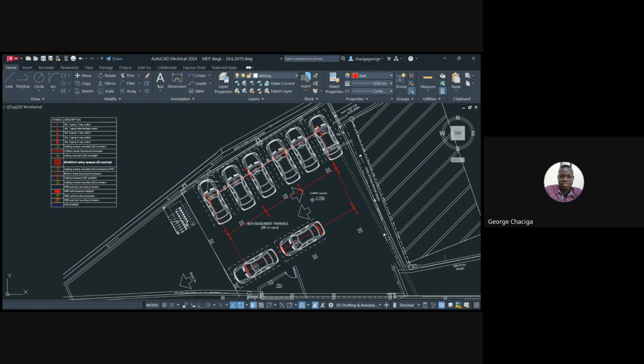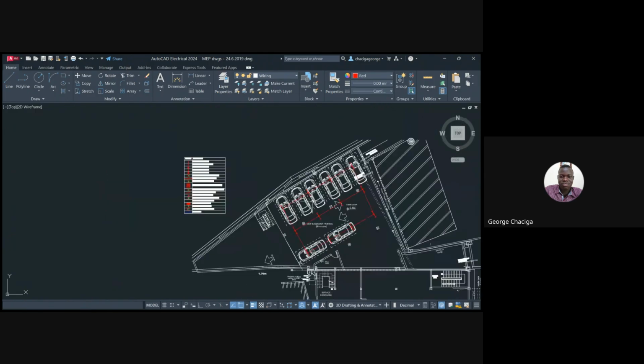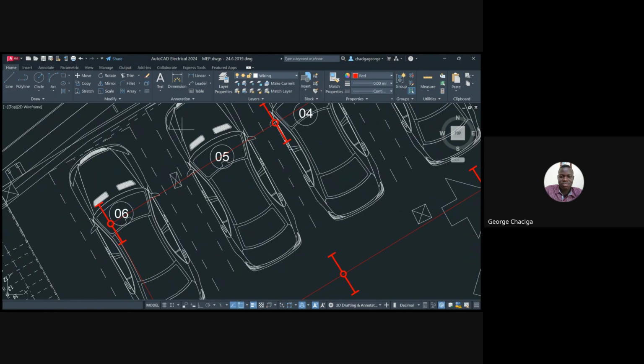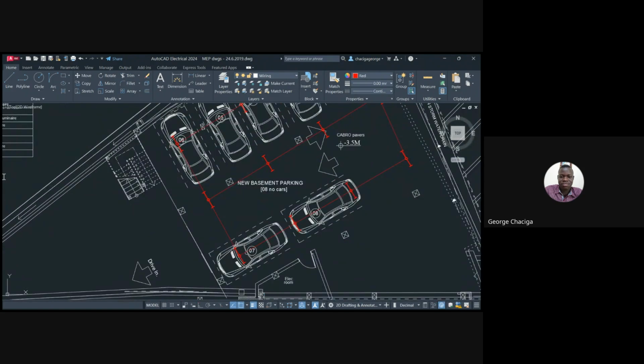So you're having a lighting. How many bulbs have we got? 1, 2, 3, 4, 5, 6, 7. So if you measure the distances between these, you would see that we have achieved our target. Our target, this spacing, which is not exceeding 4.5, I think. So in that way, we have achieved uniform lighting.